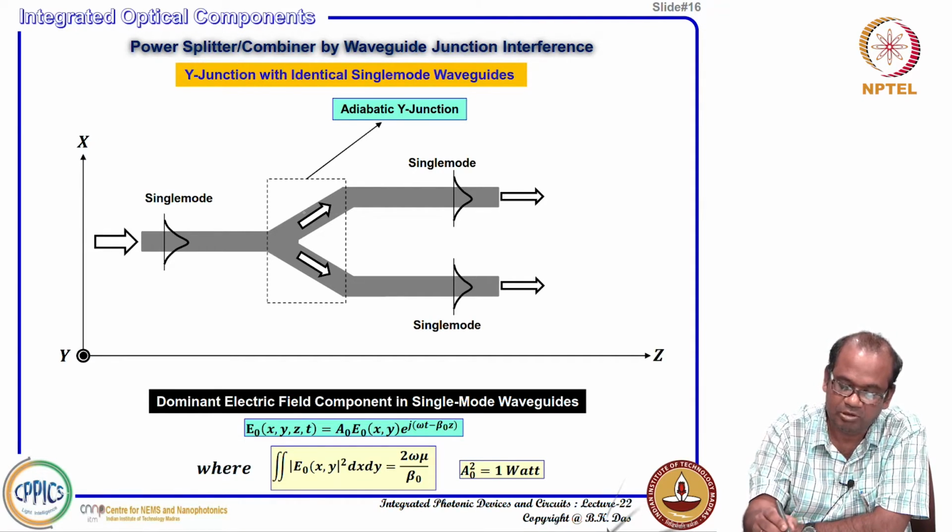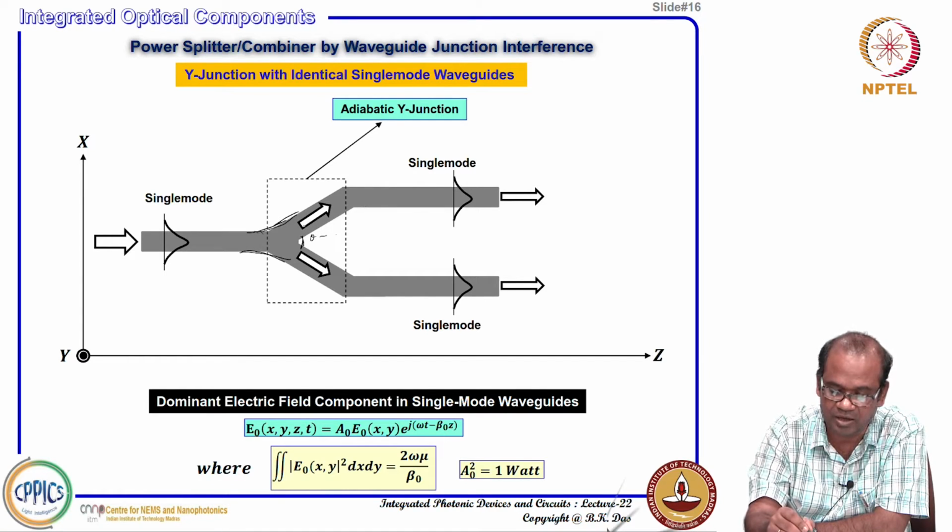What you could do is have an adiabatic junction, with a very small angle, and make it a little bit smoother instead of abrupt. So, adiabatic, with the angle close to 1 degree, 2 degree or something like that. If you make it so, then it will go smoothly, slowly. If there is bending also, you are making it adiabatic here. Okay, smoothly it is changing.